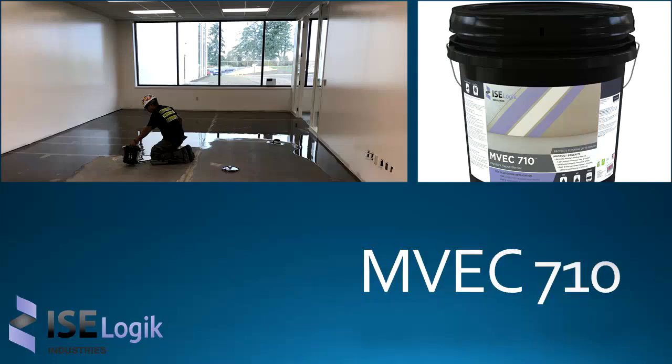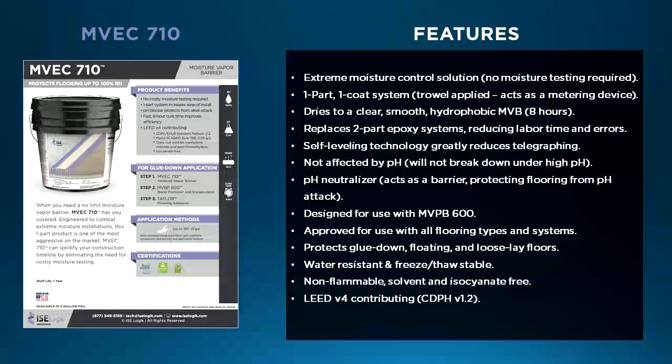Our first product we'll go into is our MVE 710. That's a moisture vapor emission control 710. This product is a single part system that you'll see in the photo there, troweling it on the surface of concrete. So this is an all-in-one, one-part moisture mitigation system.